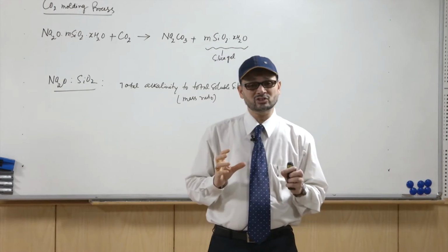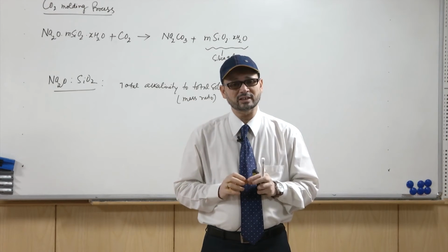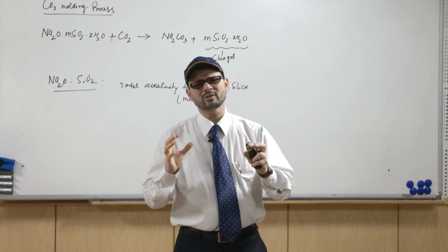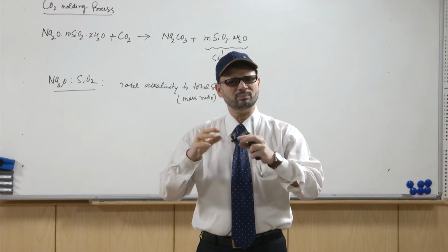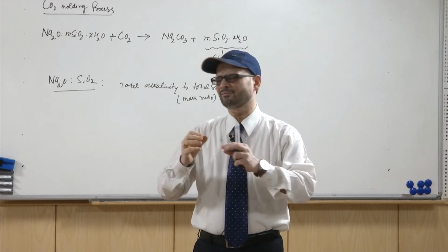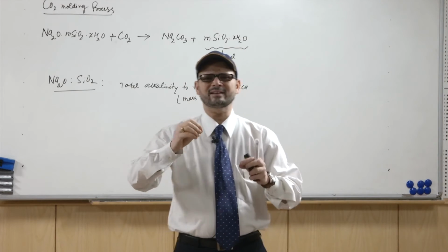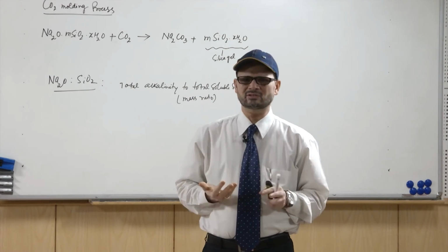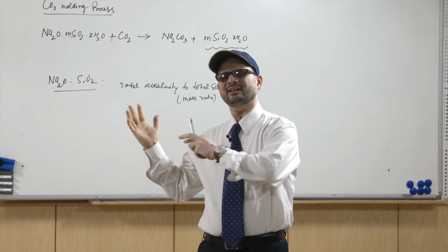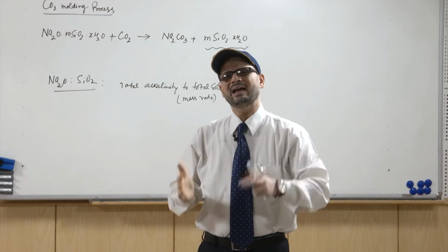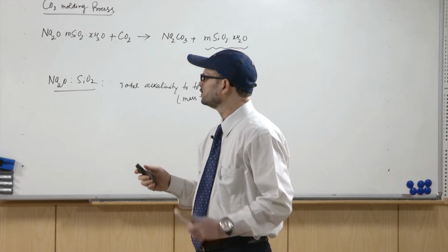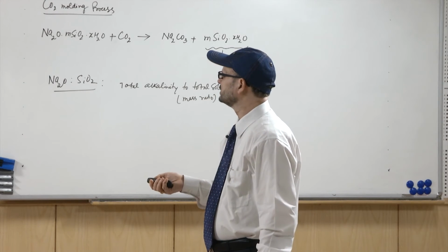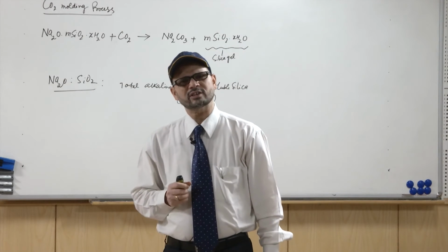Accuracy and finish is quite good in this case, because while taking the pattern out is not much of a problem. You can control the sand grains and you can get adequate strength. So, because in this case you get adequate strength and the mold stability is quite okay, your finish is quite okay in these cases.